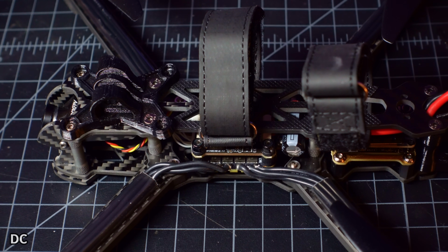And someone asked me the other day, like, what happened? What do I do? One of my motors is turning the wrong direction. And this is like a 3D printed build that a guy was working on. And I said, well, there's an old school way that you can fix that if you want to reverse motor direction without having to go into, say, BL Heli or BL Heli 32 or mess around inside Betaflight.